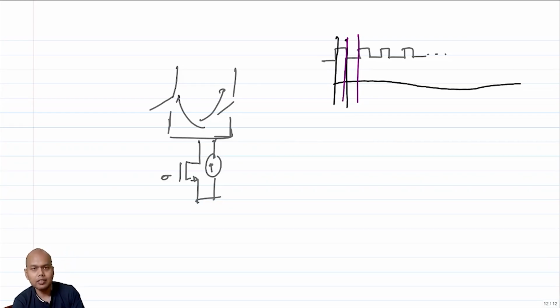It's almost like DC from cycle to cycle. If I get a flicker noise current in this direction of a certain value, I am going to get the same flicker noise current in the other arm in the next cycle. Since I am taking a differential, that gets nulled. So we do not have to deal with flicker noise of this transistor.